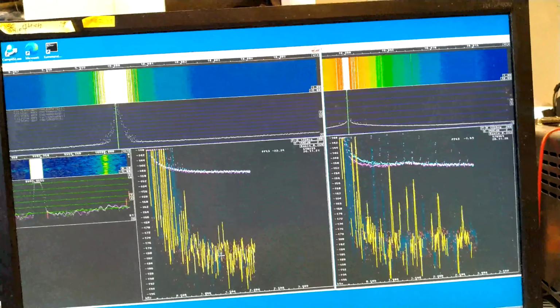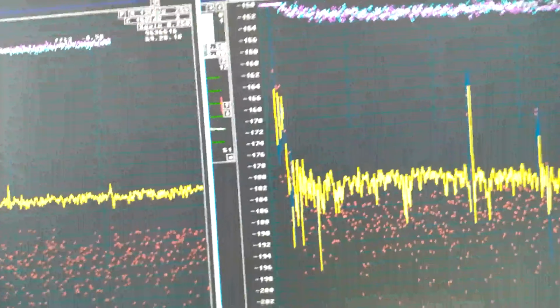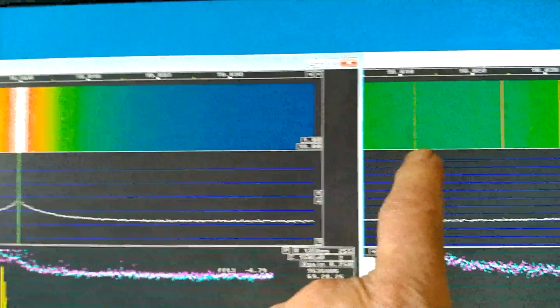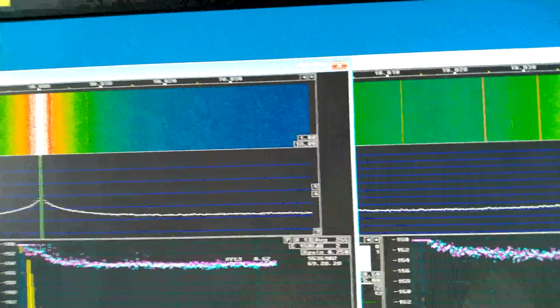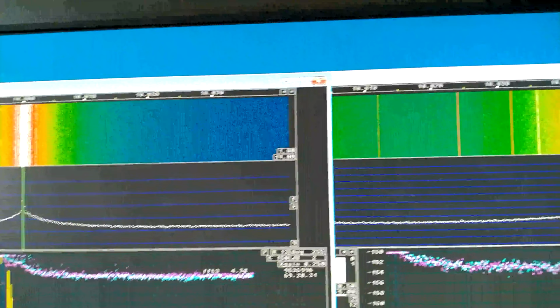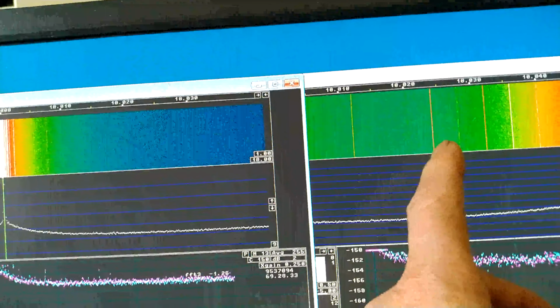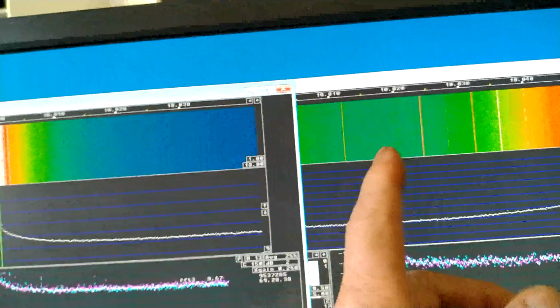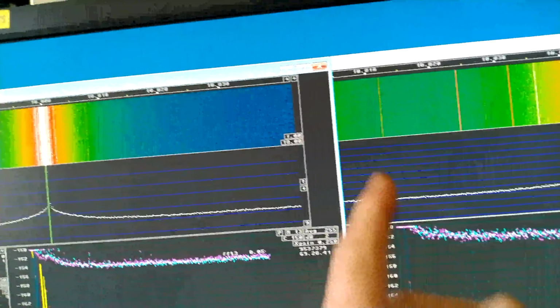So something is incorrect here, and the strongest feature that shouldn't be in place is this spur. The frequency is 12 kilohertz, and when I look at the spectrum, I see this line, a pretty strong one, at 12 kilohertz. And then I see here, with the 4 kilohertz separation, there has to be one in between here and one here that I don't see in the waterfall.